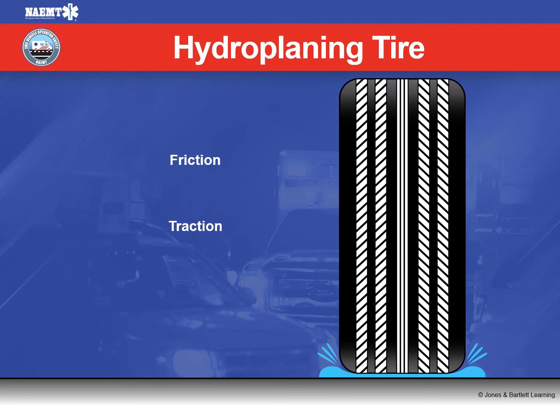So then why do tires hydroplane? Tires lose traction as a result of worn or poorly treaded tires that can no longer evacuate water effectively. When tread wear has dropped below a minimum standard determined by the manufacturer, wear bars start to become pronounced and are visible. Wear bars, when even with the surface of the tire, indicate no tread pattern left and the tire becomes unsafe.